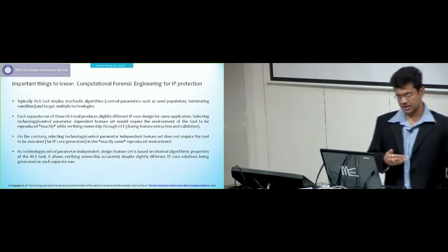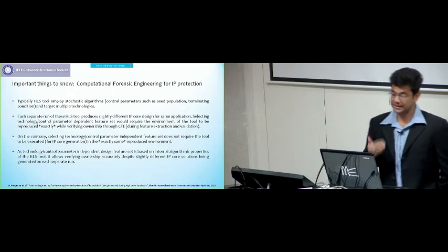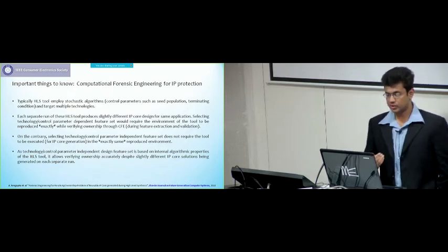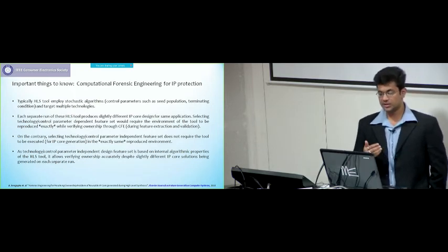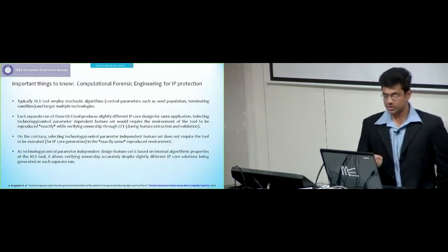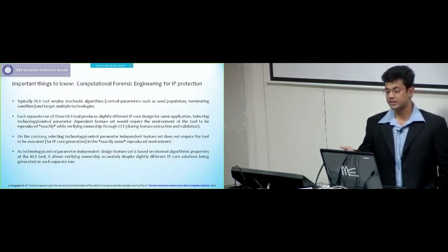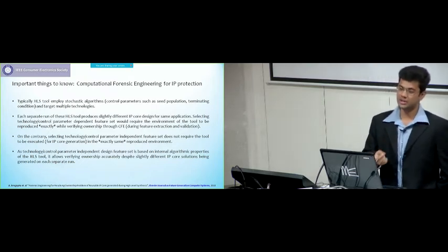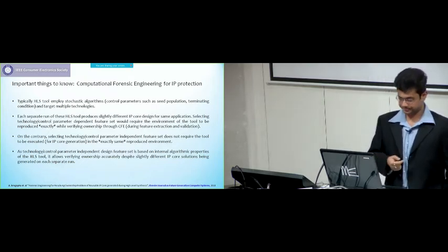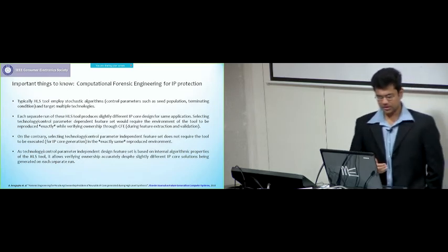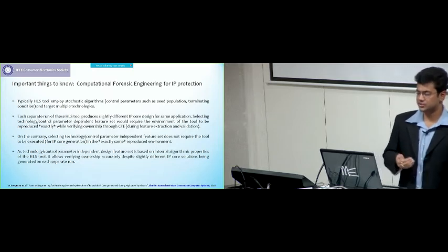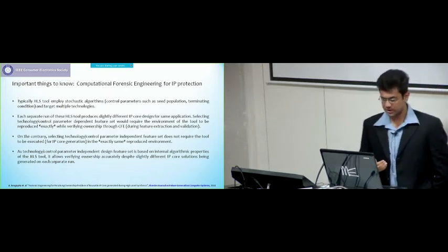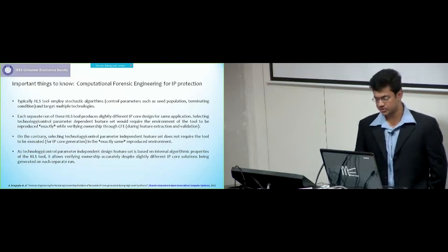On the contrary, if we select the technology or control parameter independent feature sets, that does not require the tool to be executed in exactly the same reproduced environment. So, definitely in terms of recommending what type of feature set has to be used, it is always advisable to go for technology or control parameter independent ones, so that you do not have to reproduce the environment exactly how it was done. Further, the parameters are also based on internal algorithmic properties of the HLS tool, thus it allows verifying ownership accurately despite having slightly different IP core solutions.